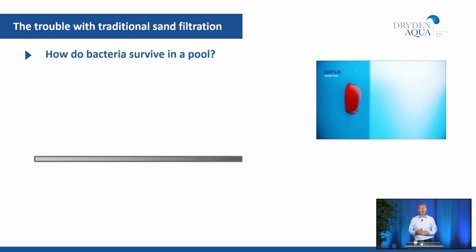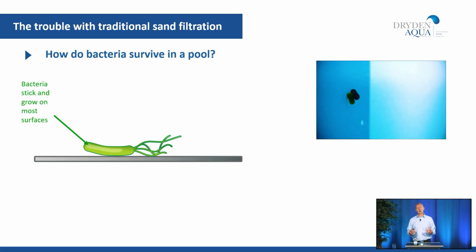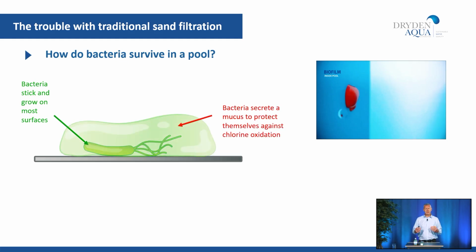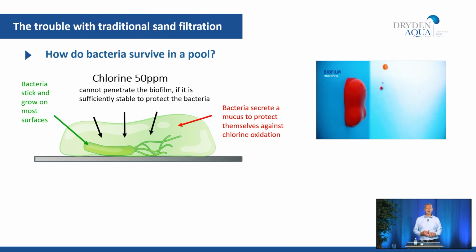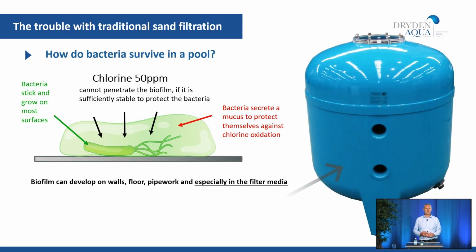So that bacteria that's in the pool, some of it can be killed quite quickly. It's quite a fragile organism. Some are a little bit more resilient and strive to reach a surface. And then once they find that surface, they then produce an alginate around themselves to protect them from the oxidizer, chlorine, in the water. And this is the early stage of a biofilm production, slime building in the pool. And we know that chlorine simply cannot, 100% cannot, penetrate this slime buildup in the system.